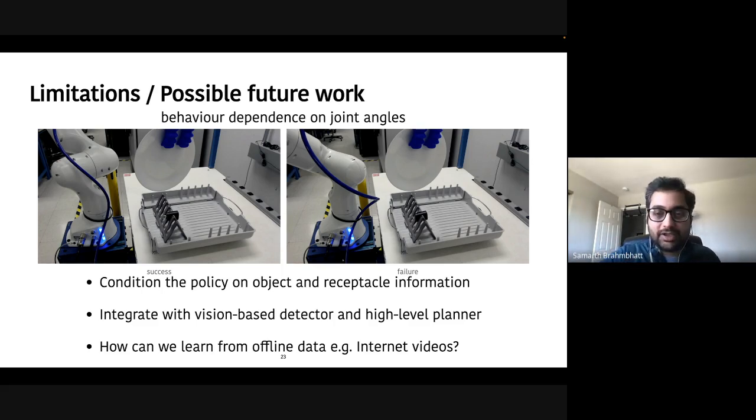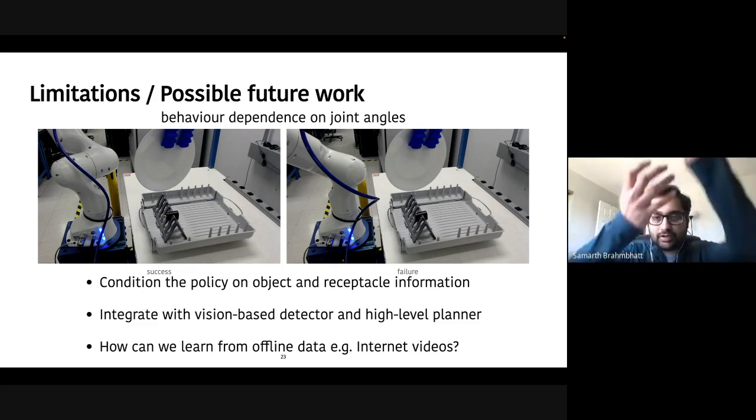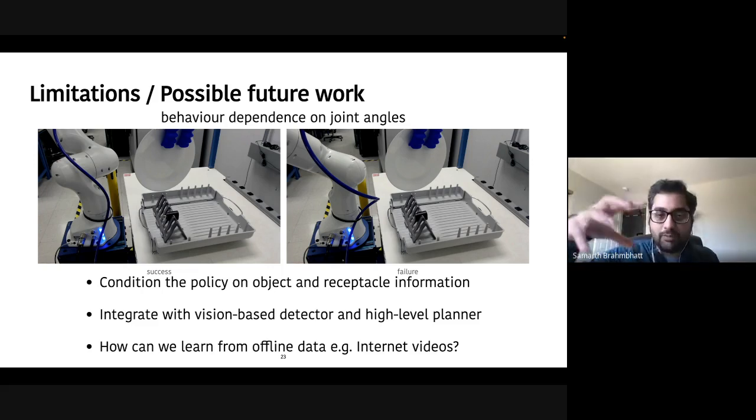We still don't need a full 3D model of the object, but if we are able to segment out the object, then we can have a rough idea about how long the object is or how wide the slot is. That kind of information is not changing at every step of your episode. Instead, you can get it from a snapshot before the start of the episode and feed it in as a conditioning variable to the policy. That way you can have a policy that can generalize to different conditions.